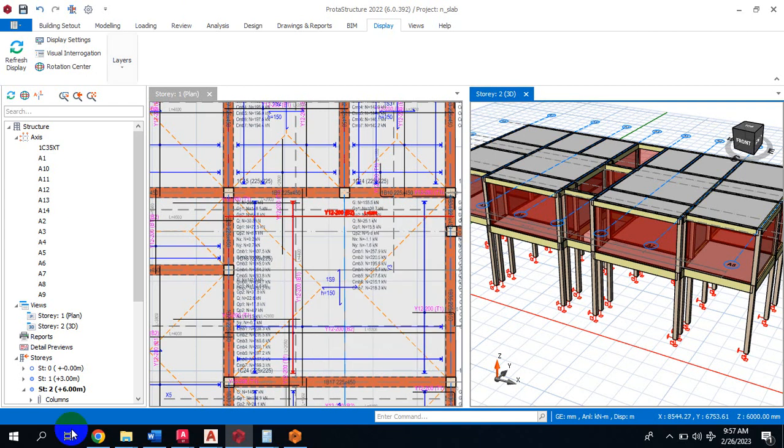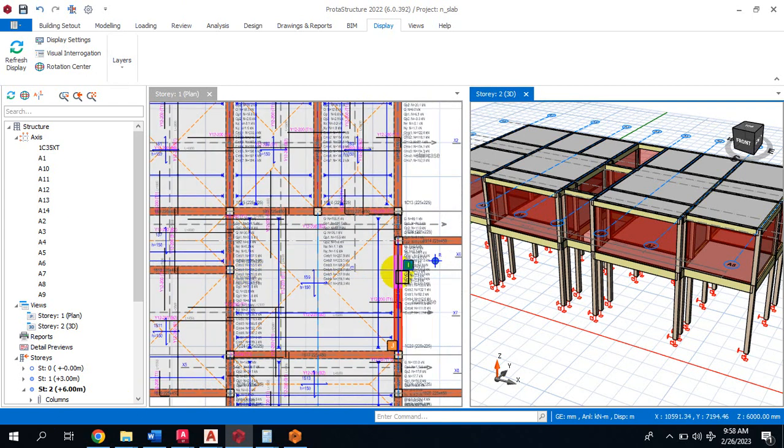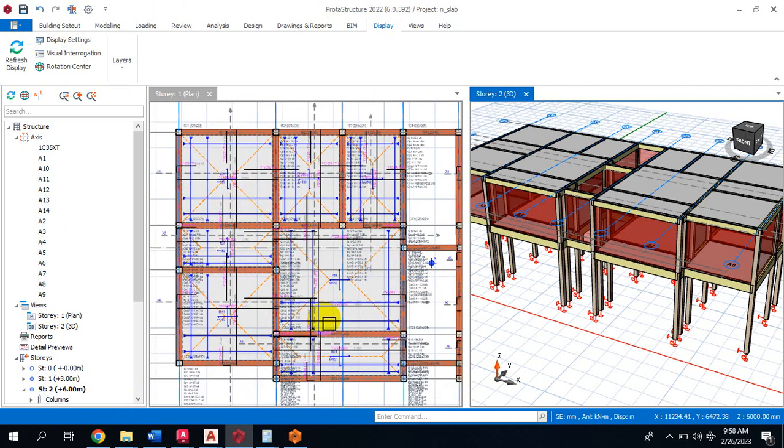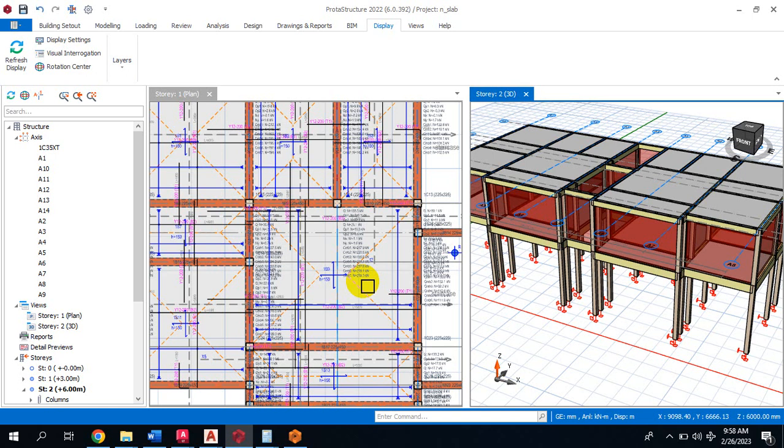But we also want to have a beam here, probably because the width of this slab is wide, and let's say there is a deflection and it's failing. If that slab is failing, we can introduce a hidden beam, which is the slab stiffness, in order to increase the stiffness there.